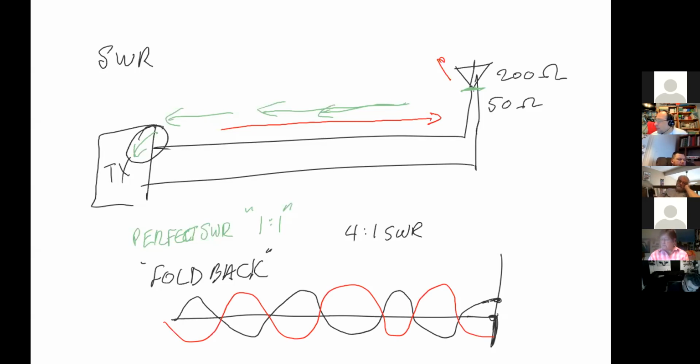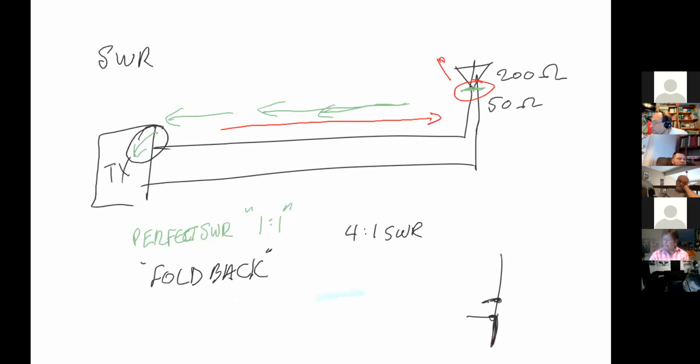The same thing happens when you have an impedance mismatch in a piece of cable, where it's connected to another piece of cable or to an antenna. Basically, you'll end up with a wave that is reflected back from that mismatch point. And that power has to go somewhere. Because there's a voltage associated with it, if voltage is being driven into your antenna by your transistors, you'll potentially end up with more voltage coming back, which can destroy your circuitry. Okay.